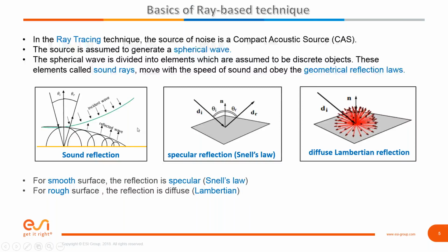You'll see we have a very efficient engine for doing this and processing this. So it's a good brute force, easy to understand technique. Sends out thousands, hundreds of thousands, even millions of rays, tracks the reflections, tracks the losses at the boundary, tracks the angles of propagation, and adds everything up at the end at one or more receivers, including all the phase effects. So it can run in a deterministic way. We are obeying geometric reflection laws with a couple of advanced, or you could say more specific, enhancements that fit in well with our solutions.